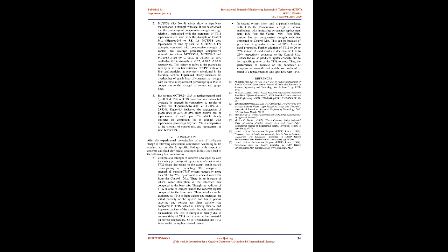4. Conclusion. After the experimental investigation of use of toothpaste sludge, the following conclusions were made according to the obtained test results and specific findings with respect to concrete and fired clay bricks developed in the study. Compressive strength of concrete developed with increasing percentage of replacement of cement with TPIS was found decreasing to the extent that it started disintegrating or crumbling.